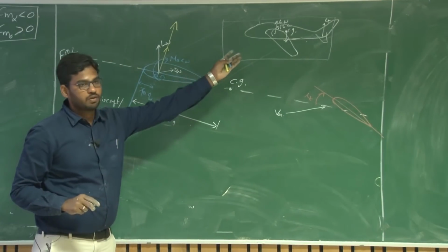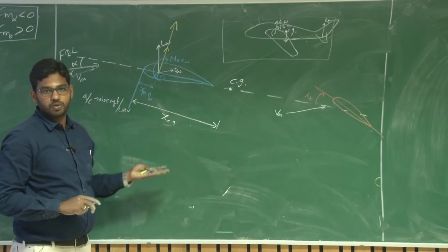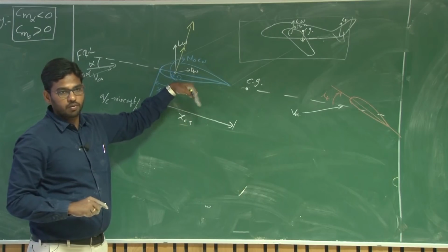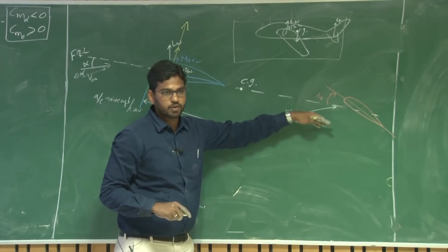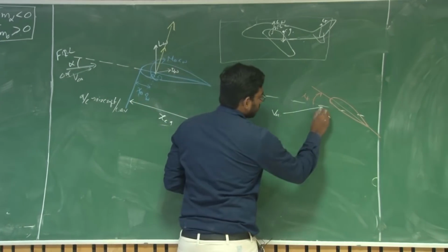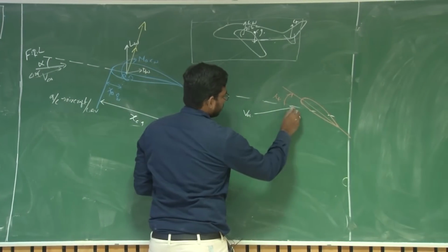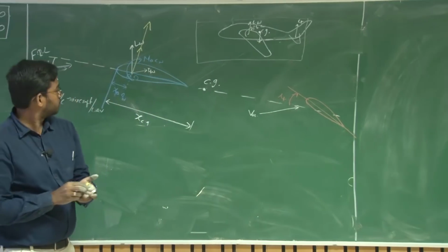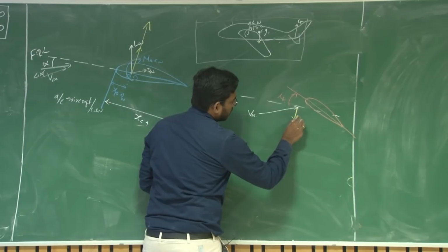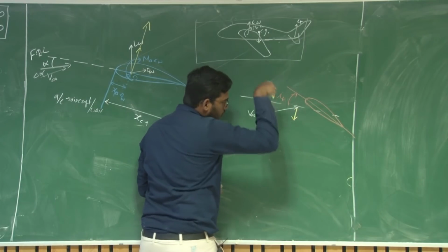But we also studied about this. This is a wing, three-dimensional wing. You have a downwash and upwash effect, right? So induced downwash, you will have an induced downwash here at the tail because of the presence of the wing. Because of which there is a downwash at the tail that reduces the angle of attack. What is downwash? This is the downwash, that is a downward flow.